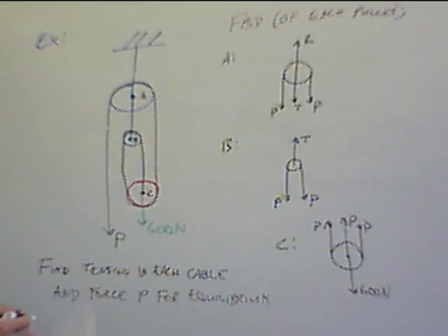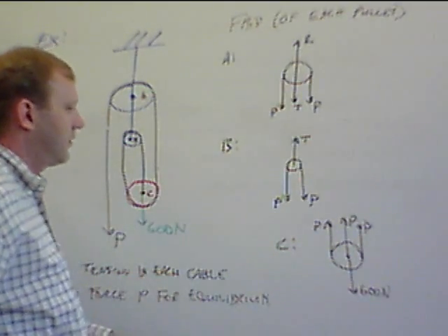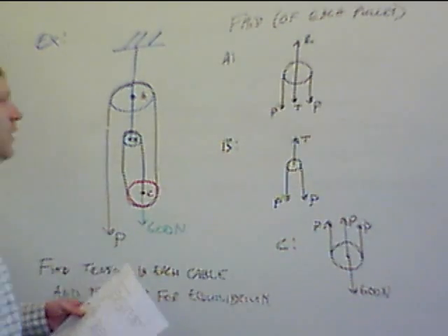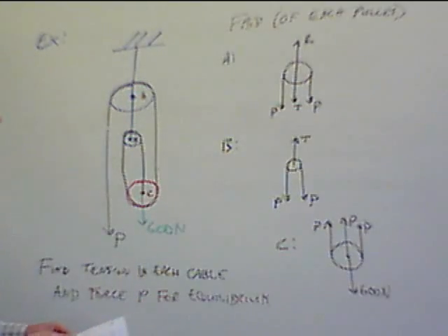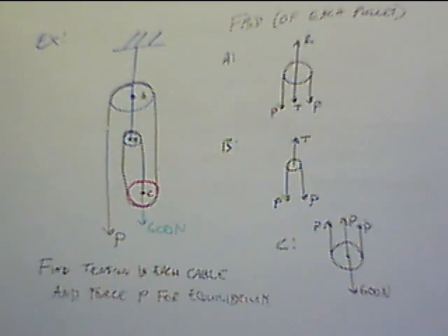Again, we're assuming all these pulleys are frictionless and of negligible weight. So this allows us to take a look at this. And now we're going to apply the equilibrium equations to each of these 3 pulleys, to solve for each cable tension and force P for equilibrium.